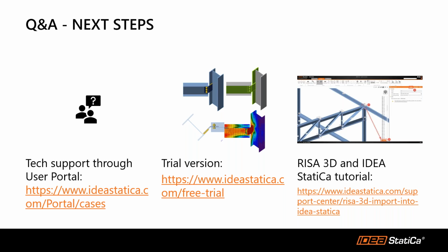Another question: they're asking why split the member. So you had that scenario with the angled beam where you split the member, and they're asking, is it to input loads for equilibrium analysis? And they're saying, instead, can you not evaluate that connection with just the member and reactions of the connecting members and allow the continuous column to just have an unbalanced reaction?